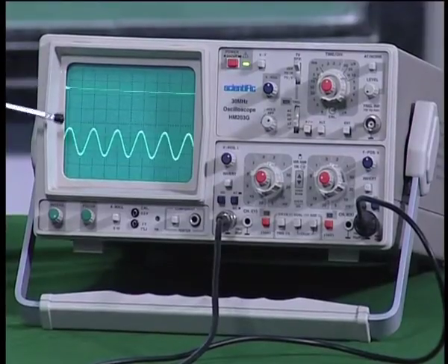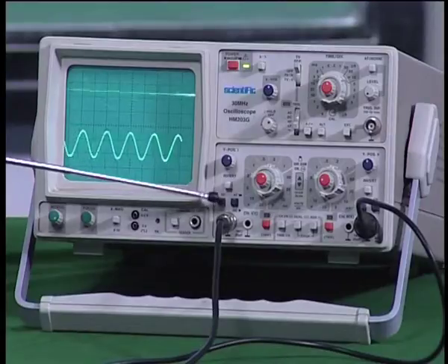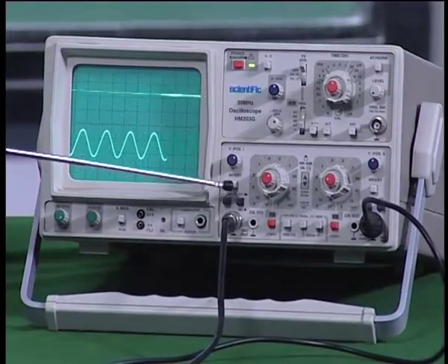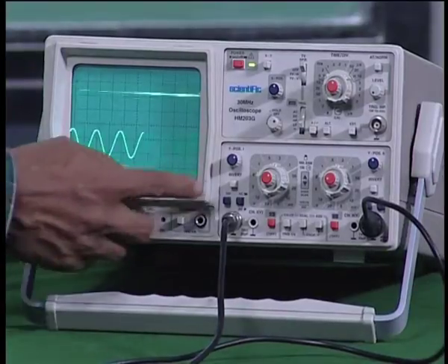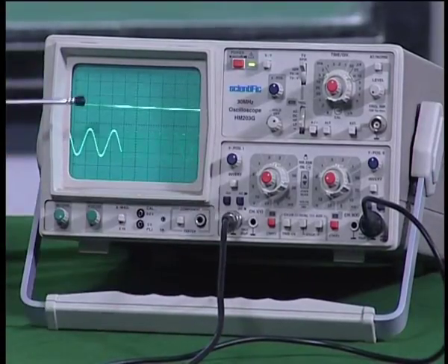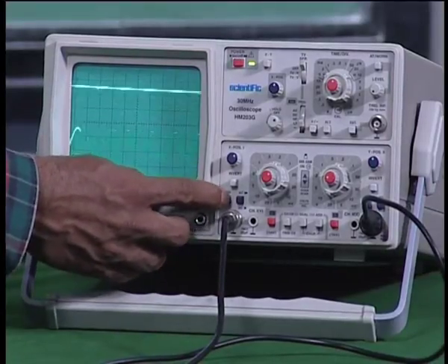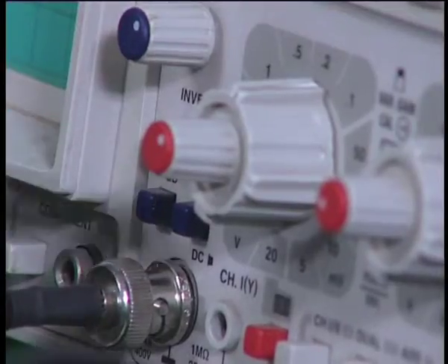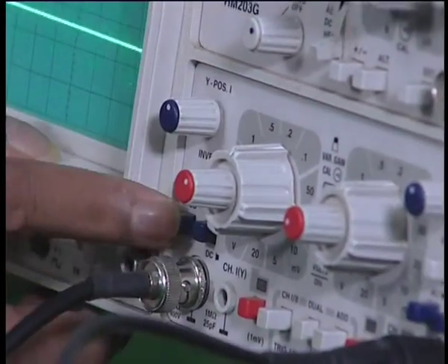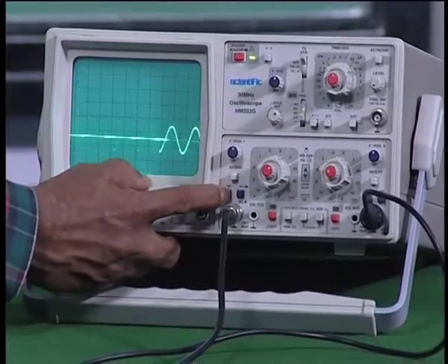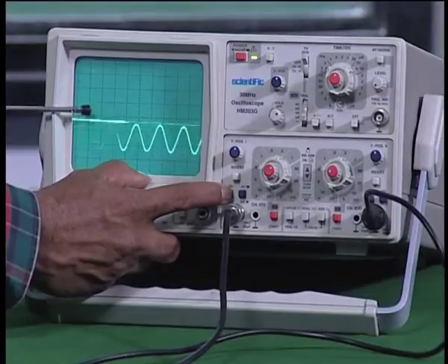But how much is the DC you can measure by using the DC key here. If I press the AC and the DC key, now it is in DC and now it is here. If I now release that, if I make it into a ground, you can see the signal comes at this point. If I release it, it goes up. So, that much is the peak. Now, what I will do is I will bring it at the bottom or at the center, and then you can see it is actually going up to the peak value.